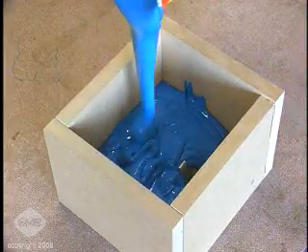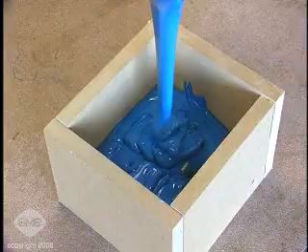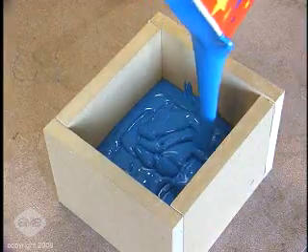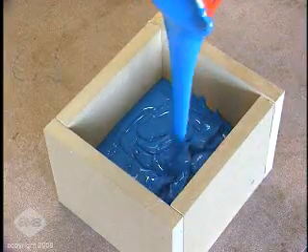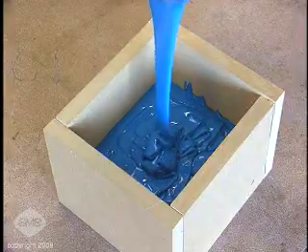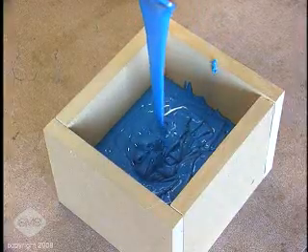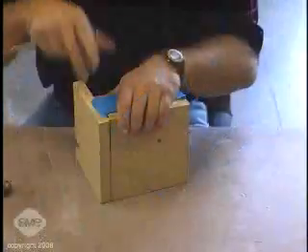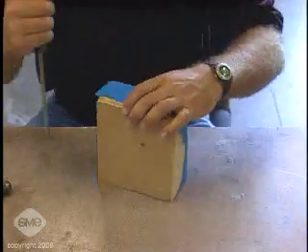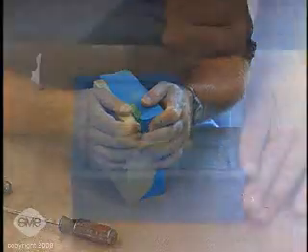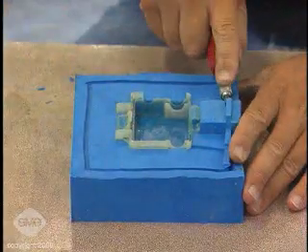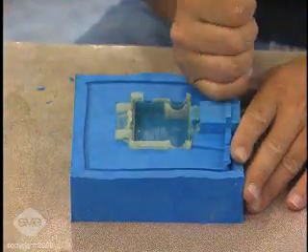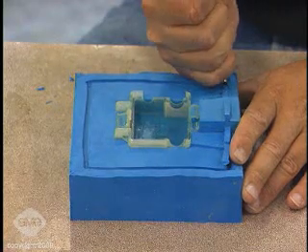Typically, it is necessary to apply a vacuum to either the RTV molding material before pouring or the tooling assembly after pouring to remove air bubbles from the molding material during curing. Once the silicone has cured, the box is removed, and the mold half and pattern are prepared for the pouring of the second mold half.